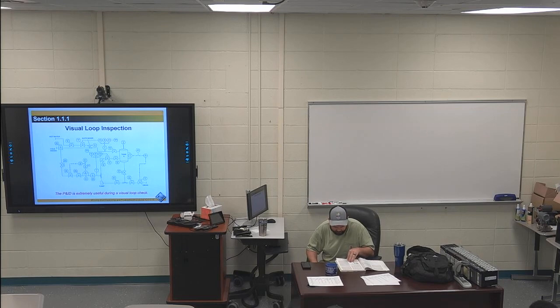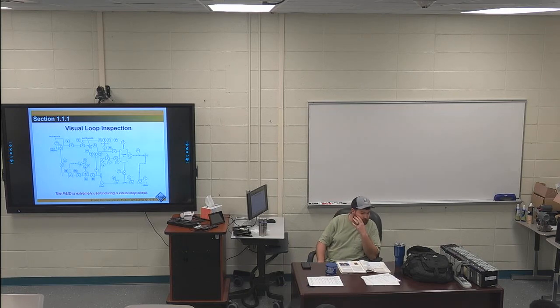Control loop components, 115, nothing in that. But do note, for a lot of control rooms, especially if you're working nights as a maintenance person down here, air conditioning is super important. I know when I was at the steel mill, we had air conditioner units go out in our big MCCs and PLC rooms. PLCs have a sensor on them. If they get above a certain temperature, they're going to shut off.